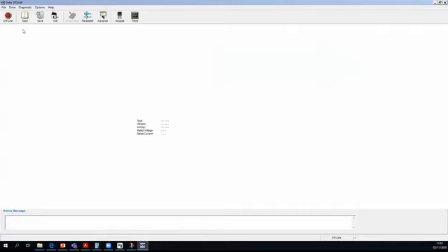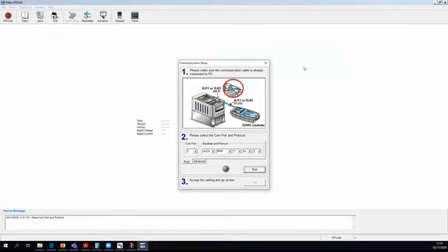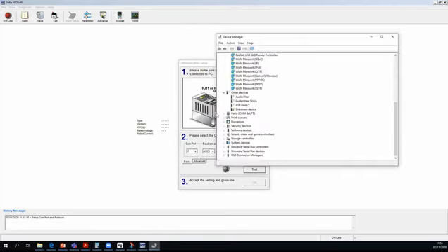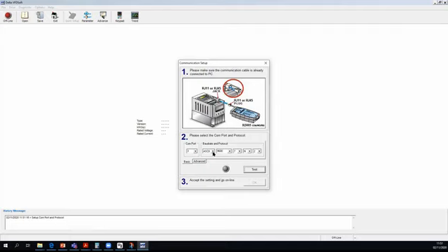Okay, so firstly, you just need to find out which COM port has been assigned to your drive. So you can go to Device Manager to find out. So in this case, it will be COM port 3. And this is the default address of the drive. And you can change this if you want from parameter 9-01 and 9-04. So I'll just do a quick test. I can see that yeah, I'm connected properly with the drive based on this green LED.